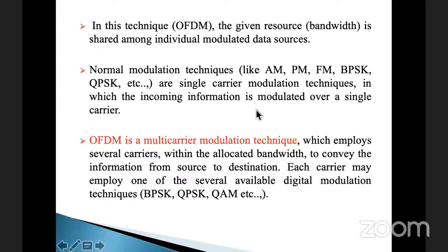So with this frequency selective channel, I cannot proceed because it creates a lot of interference. To avoid this, we still want to go with a narrow band, but the same band multiple times, since I have a huge bandwidth. This huge bandwidth is divided into smaller bands, and in each band I will send my information in parallel. That's what I am interested in. That comes under OFDM, orthogonal frequency division multiplexing.